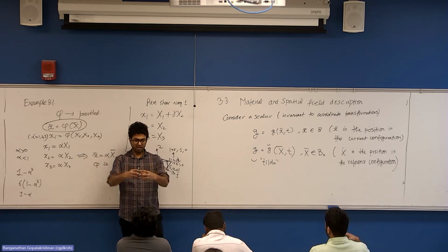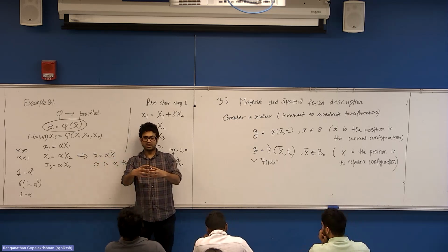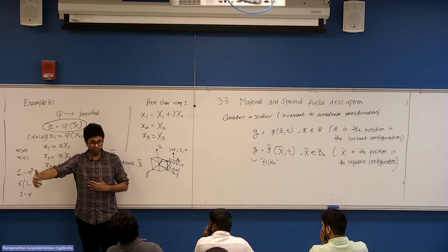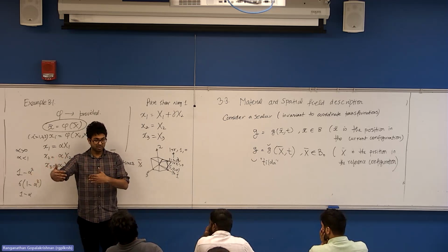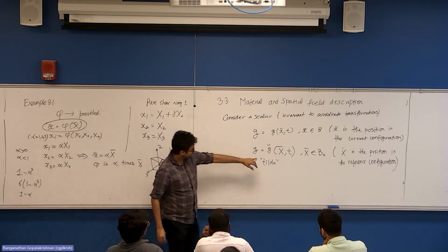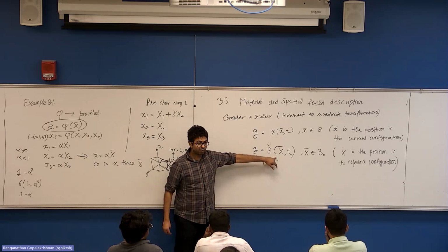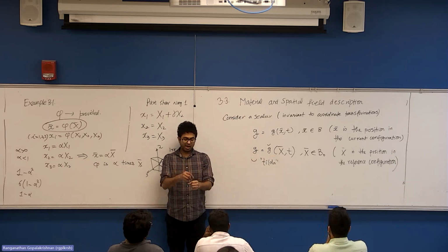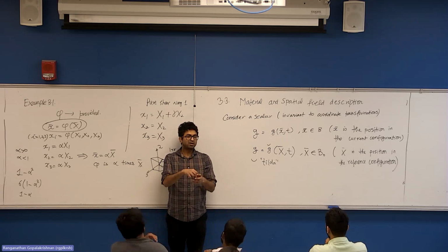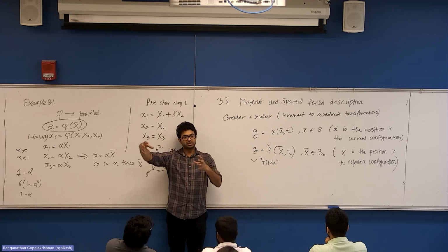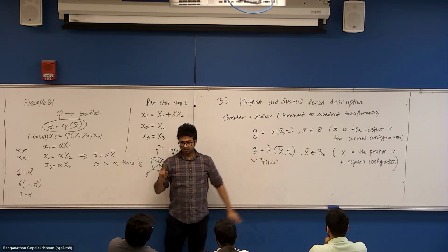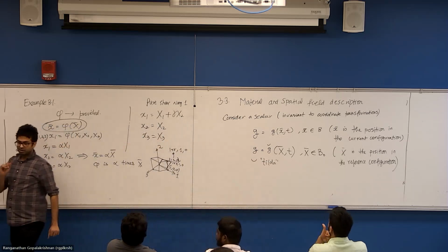It can be divided, like initially you have a blob of dye, that dye is then distributed, it just becomes dispersed in a larger volume. So there are shape changes, there is motion, there is deformation, and all that is described in the reference coordinate. What is the reference here? At time 0, I drop a blob of dye. That is my reference configuration. From that configuration, how does the dye change in shape? That is my interest. That becomes the material description. Okay, with me so far?